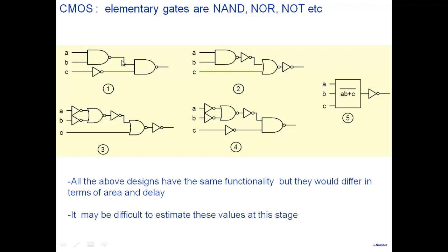So delay, you don't have a precise idea. Okay, what delay will this particular circuit give me? Even if you know the delay of an individual NAND gate, because the wires are not available to you. The wire delays are not available to you. Also, let's discount that particular problem. Let's say I have a schematic which is here. And let's remove the wire delay problem for a bit. I know the delays of each one of these gates. How do I check whether my circuit will work with that delay constraint?